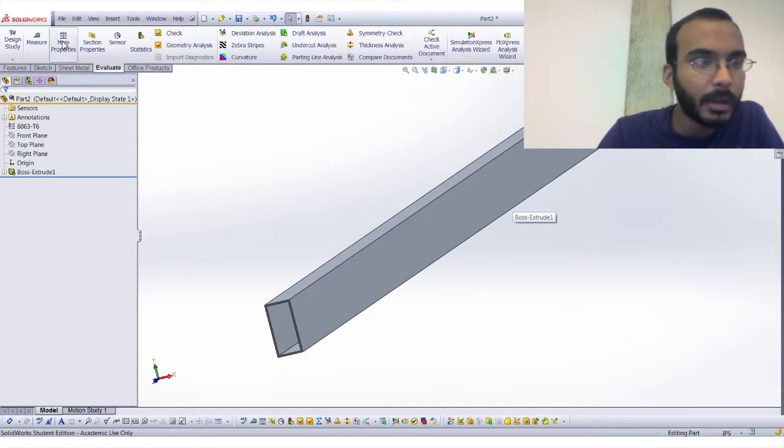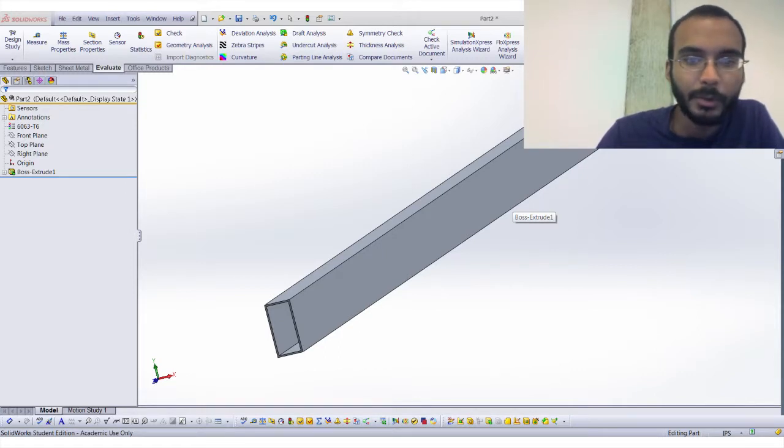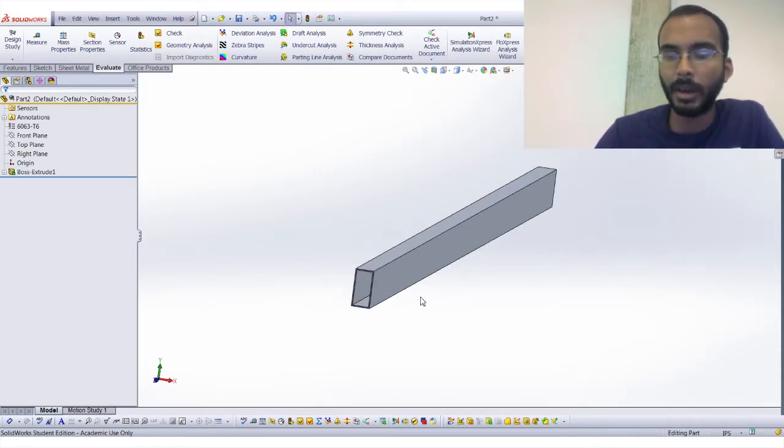What else? Next to that is mass properties. So this is how everybody, if you CAD your full robot, you can get a pretty accurate description of how much you think it's going to weigh. So this 8-foot huge piece of aluminum weighs 13.5 pounds almost. And it's pretty good on density. So it's basically using the material density, figuring out the total volume of the actual material there, and does the calculation.